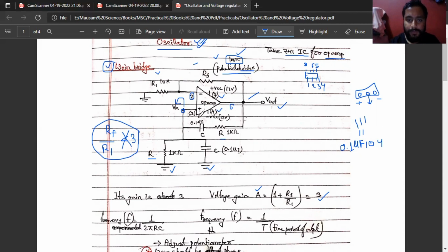In an oscilloscope, we connect these 2 points with the 2 probes. One probe will be connected to V in, the other probe to V out. After that we can see the input voltage and output voltage there, and we can find out the gain. Voltage calculation is easy in an oscilloscope.